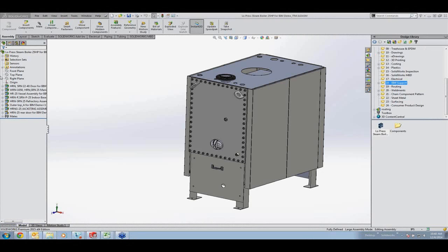There is now a new option here that when you mirror the part, it will maintain the sheet metal information in the flat pattern. In the past, when you mirrored your sheet metal part, you might see a flat pattern where the bends are off the sheet somewhere. That is no longer the case in 2015.